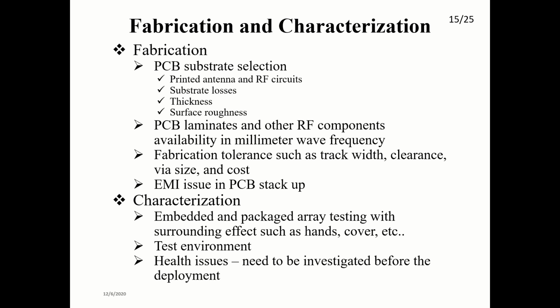Next is the availability of PCB laminates and other RF components at millimeter wave frequencies. You can design any component you want, but it should be available in the market, right? You can come up with a fantastic design with some laminates, but finally when you explore the market, it will not be available. Then your entire work is lost. So please make sure that whatever components you use are available in the market.